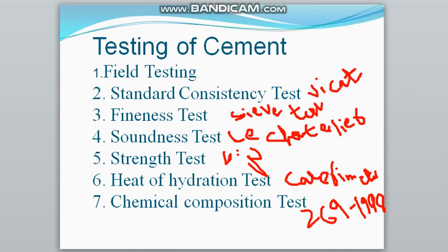The cement should not contain any hard lumps. Lumps are formed by absorption of moisture from the atmosphere. The cement should feel smooth if you rub it between your fingers. If not, then it is because of adulteration with sand.